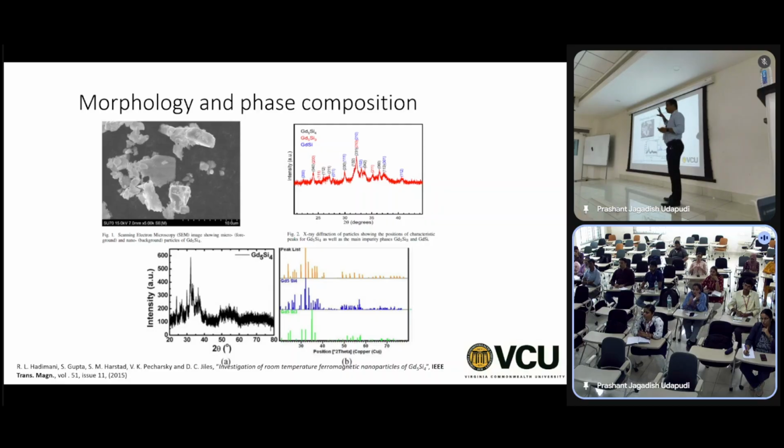At high temperature, it's monoclinic, and 5,4 is orthorhombic, and when it's orthorhombic, you have lots of planes, so you get these really complex peaks, and it also has a small phase of 5,3, a small phase of 1,1. So this is what we want. That is the major phase, but there is some impurity here. Okay, so those peaks we can see. The red is 5,3, the blue is 1,1.